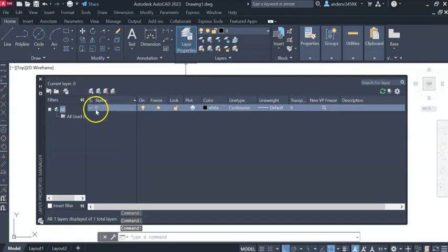We've been drawing on layer 0, which you shouldn't do, but anyway, that's not important for your little exercise. And the lines were white. Because the background is white, it draws it black, and the lines are of a continuous line type. We need to change that now.